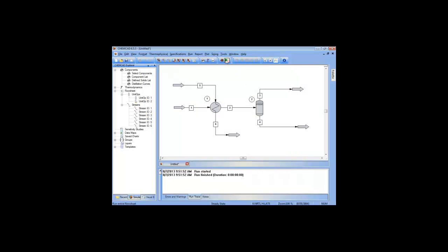So click OK. Now in this case, let's do a run all. We can come down here, and we can see we've got the 250. Our vapor mole fractions are hovering closer to the 50-50 range. So we've got roughly 500, a little over 500 pounds going out the top, most of that more so ethanol. And we've got a little under 500 pounds going out the bottom, again more of that water.